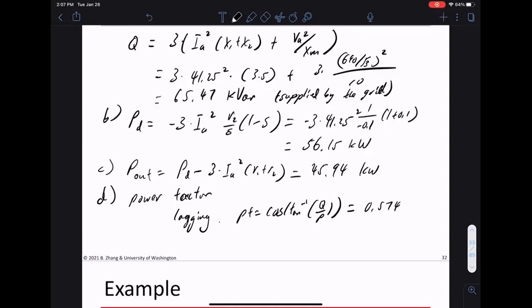So that's why the type 1 turbine, for both reasons, that you need a synchronous frequency and you need reactive power, is not going to work in a standalone system. It cannot be the main power provider in the system. It cannot maintain frequency, you need outside frequency, and it cannot provide reactive power. If you listened to the talk earlier this morning, this thing is not very grid forming at all. This is not something that will support your grid. It's not something that will keep the grid going.